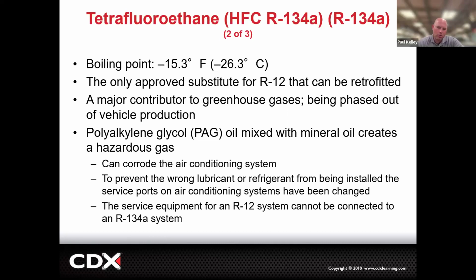You got to get rid of the R12 refrigerant appropriately, not vented to atmosphere. And then you got to put the R134A fittings in, charge it with R134A, and oil it with an oil that's compatible for both. PVE oil. I'm gonna think about that just a little bit more. I'm gonna probably randomly think of it, but I can't remember.